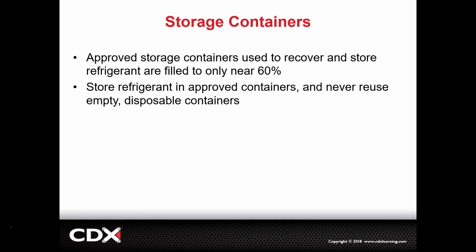Cool. And then storage containers, just FYI, we don't ever fill them over 60%. The reason why, picture a propane tank. Propane tanks, we do the same thing. It's going to be in liquid form, and then we need a little area at the top where it can expand and contract. It'll also be a vapor on the top, and we're going to pull vapor from the actual top of the tank. You can't have it 100% charged because as it heats and cools, it'll increase and decrease pressure. We need to leave some space in there.